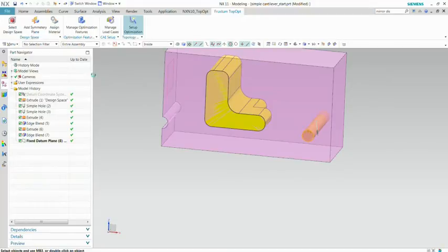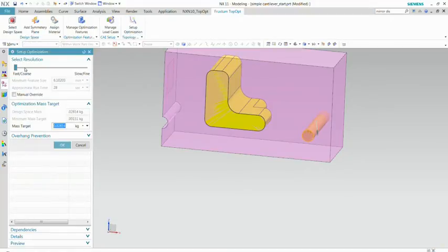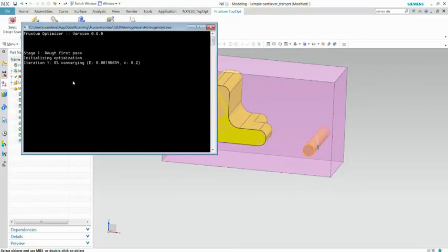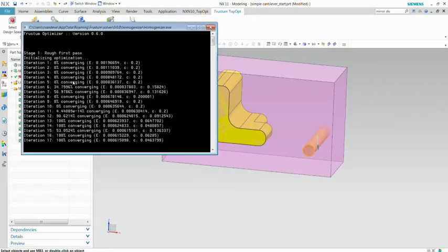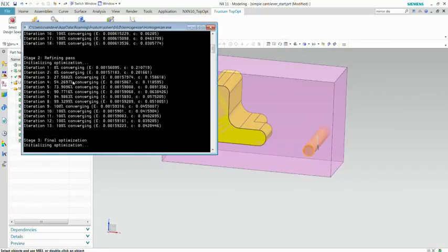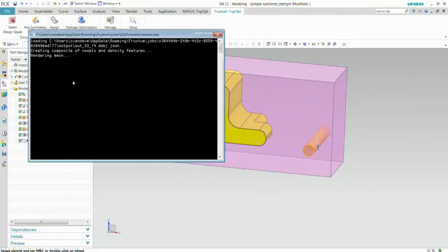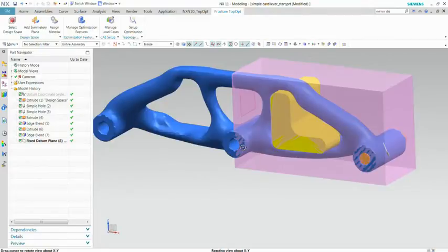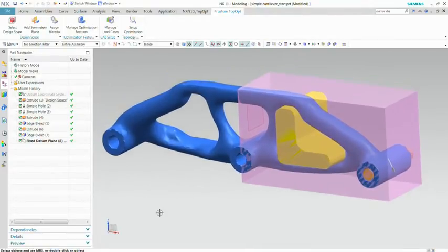Finally, I'm going to define the setup of my simulation. I didn't apply a maximum displacement or something. I'm just saying, well, try to have an optimum shape when the weight is divided by 4. And we can define the precision of our results. So the more fine we make, the slower the simulation will be, but also the more precise the result will be at the end. I'm going to show that in a minute. So it's a live solve. I didn't pause the movie, and here you see already the optimized shape.